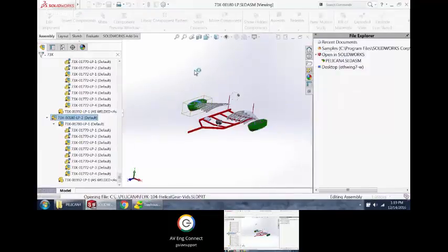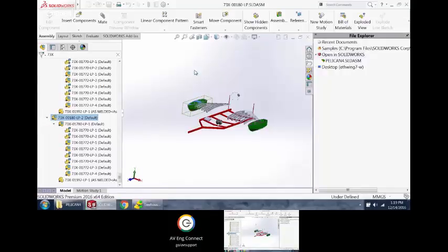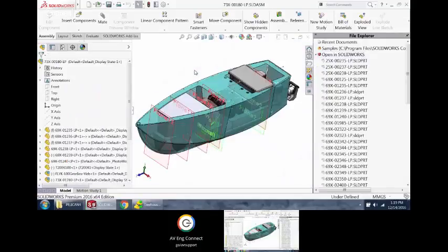I can open files directly from large design review. When I do that, it does open them up resolved. You can usually tell if something's being loaded resolved. You'll see down at the bottom of your screen it loading up a lot of items. But take a look. This has loaded up fully resolved. It's not in large assembly mode. It's just in regular old SolidWorks fully resolved mode.